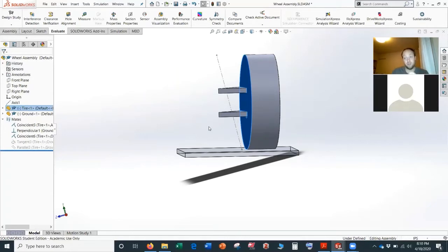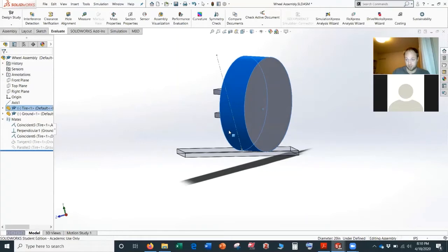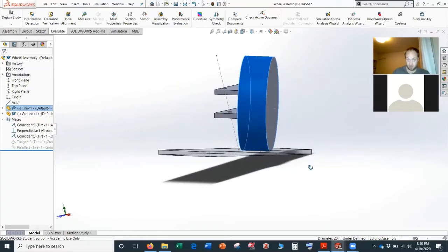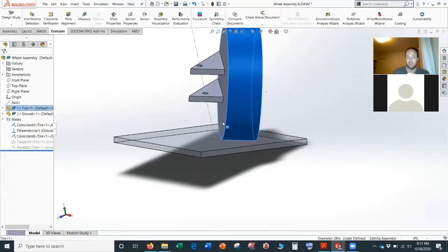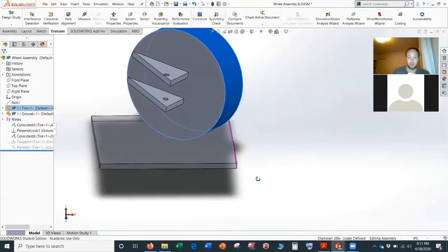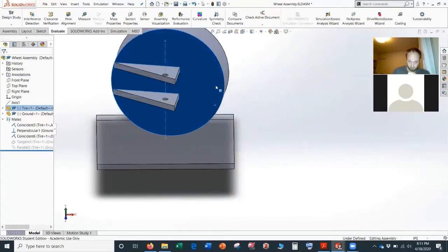It adds steering effort because you literally have to lift the car up as you turn the car, and it's going to move your CG up, right? So in a turn, it's going to move your CG up, and you also see it also brings your tire down on edge, right? So it also kind of will add some camber to your tire in a turn, right? So there's all of that to contend with, and then